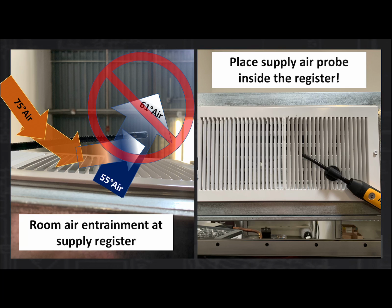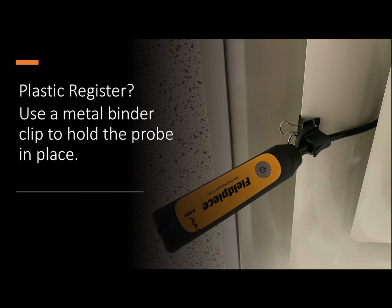So on the right there, you can see I have just spread apart the register vanes a tiny bit so I could get the probe inside of that. And now I got a really, really good supply air measurement. Now, if you don't have a metal register, right? We hear this periodically. People say, hey, the magnets don't work because I got plastic registers. Well, then use a metal binder clip, just like a paper binder clip, and clip it to the register and then stick the magnet right on the side of the binder clip. And that'll hold you in the register. And again, this is just a supply register, and you can see that probe's again up inside the ductwork.